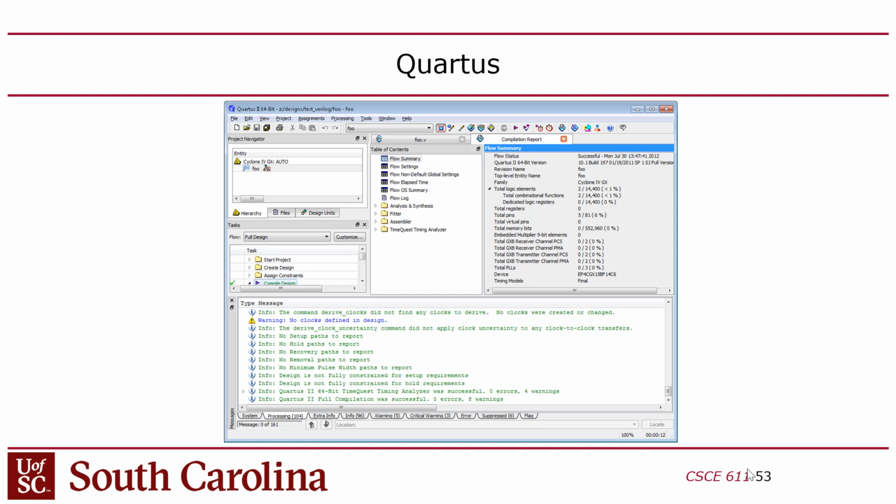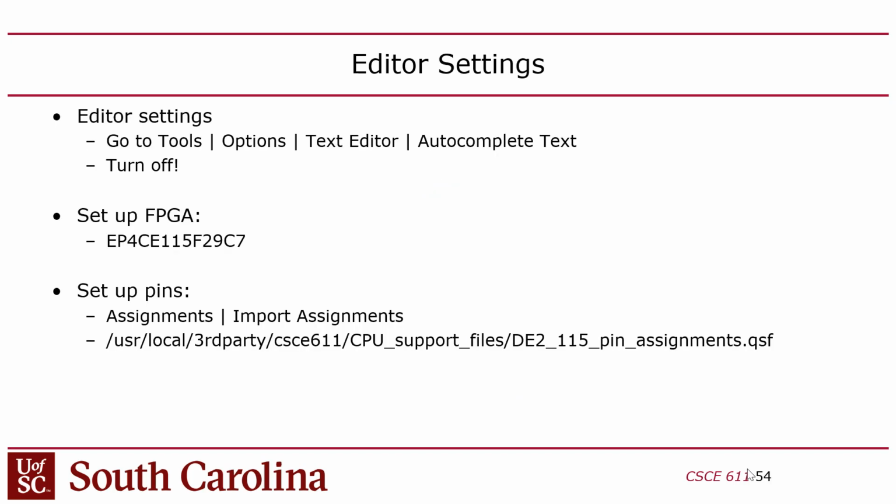So sometimes that happens. But other times what happens is you'll have a latch in your design. You'll write code that implies a latch as opposed to a flip-flop. A latch is a level-sensitive memory element. Hopefully you guys talked about that in 2.11. And sometimes you can't put latches on an FPGA because there are no primitives for latches. There are only primitives for flip-flops, edge-triggered. So sometimes stuff like that happens, right? You'll have some behavior in your code that is not implementable using the primitive circuits on the FPGA, and therefore it won't work. And sometimes you'll get an error, but you might miss the error, or maybe it'll be a warning. So that's an example. In that case, you may want to go in and use Signal Tap.